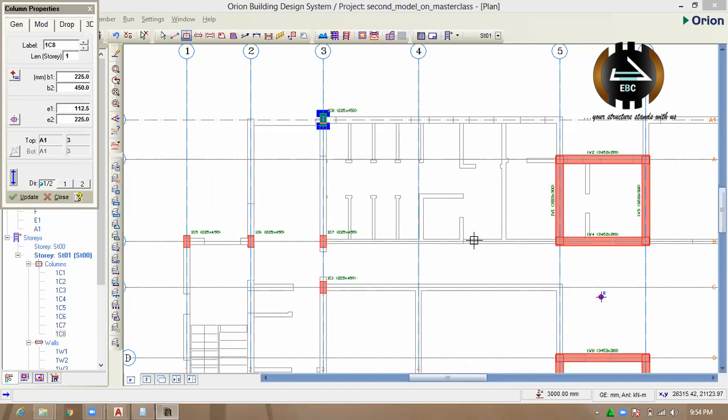The shaft on its own is self-sustaining, standing on its own. Like a work I am doing presently, the last part of the basement, that is facing the earth, I retained it. And it's all retaining wall. There is no column there. What is a column coming to do beside the retaining wall? I just have to push it off from the retaining wall.